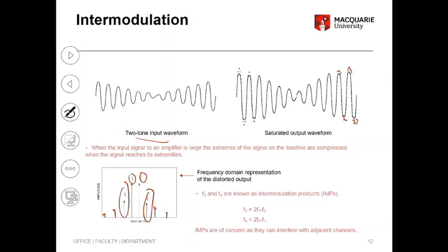Now, this is where it gets very interesting and important to remember. So the two tones that appear next to the main signal, we call them third order intermodulation product. Okay? So that's the reason why these are called third order IMD. Okay? Now, there's a way you can calculate what frequencies you can expect an intermodulation product.